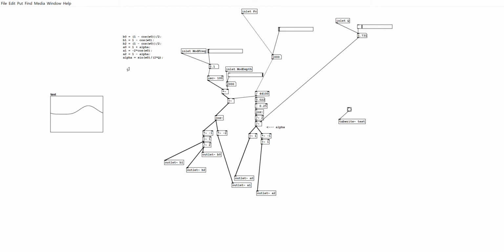So this is our guide here. These filter coefficients, or the formulae to generate them, come from an AudioEQ Cookbook text, and it's very common for DSP hobbyists to use this text. You might have come across it. I'll link it in the description. These coefficients specifically are for a low-pass filter. There are slightly different coefficients for different filter shapes, and you can implement them much the same as I'm going to show you how I've implemented these.